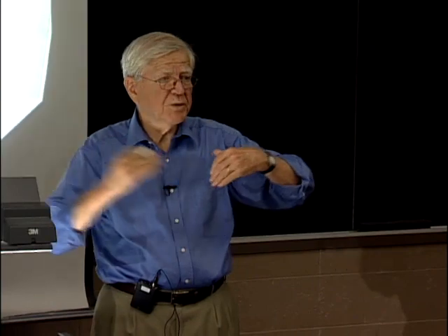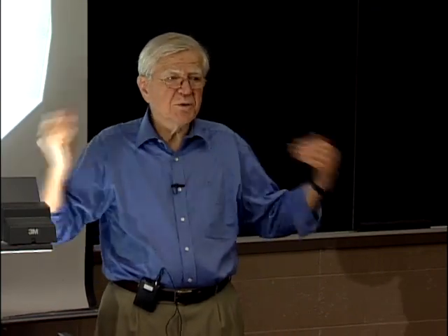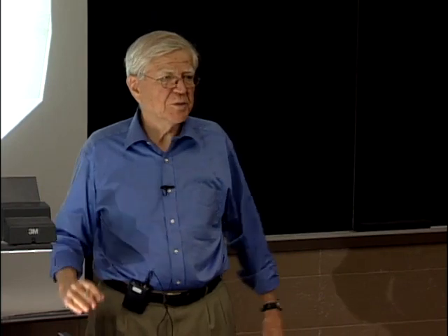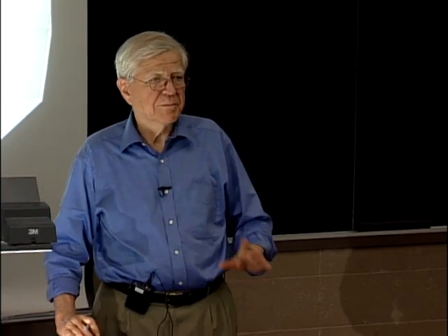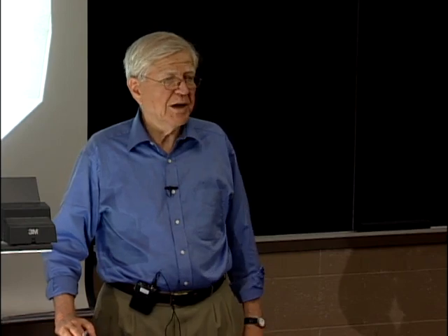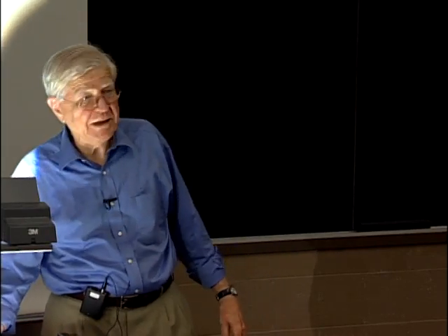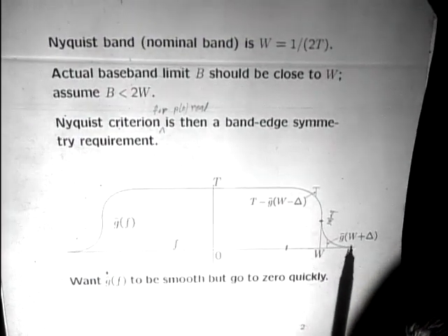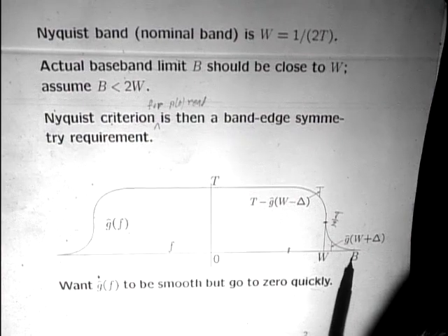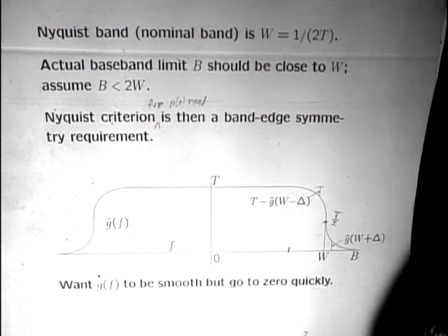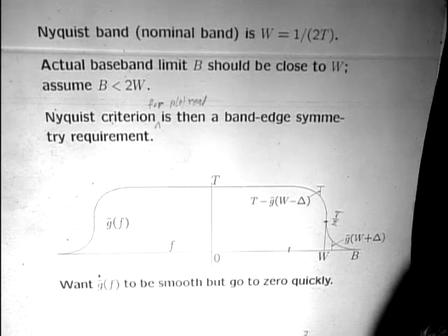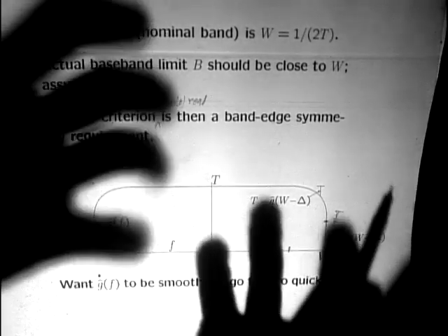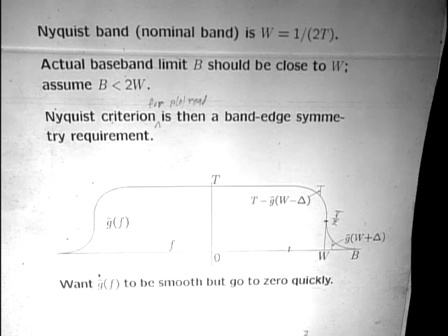Okay? In other words, we're starting out with a sequence, we're going to a waveform, and then we're trying to get the sequence back from the waveform. So it's really the opposite kind of problem. And here the whole game, namely the thing that Nyquist spotted back in 1928, was you could use these out-of-band frequencies to in fact help you to get rid of this inter-symbol interference. Because all you need to do is make these things add up to this so that you have something rectangular, and then when you do the samples, you get the right samples. Okay?